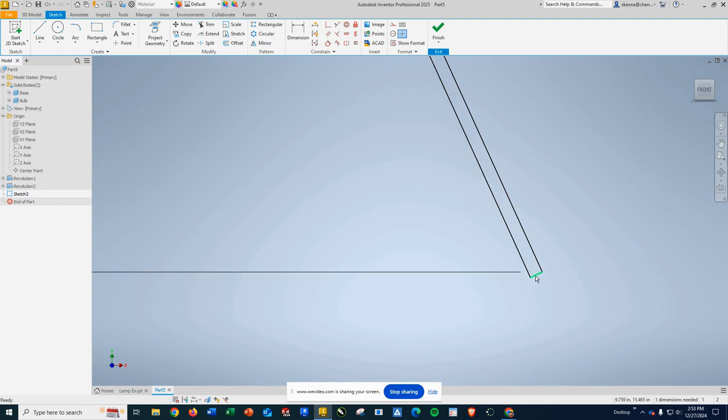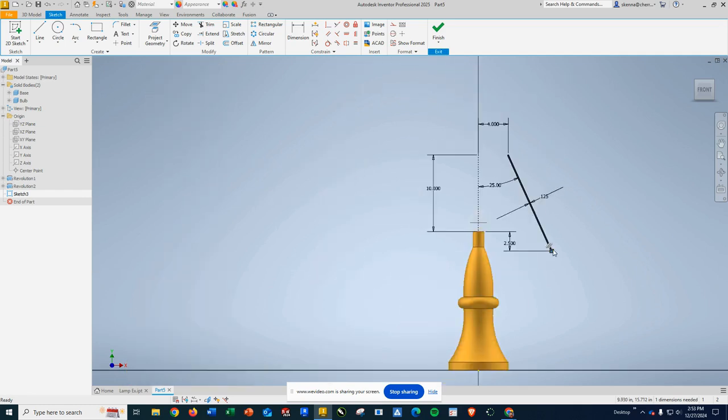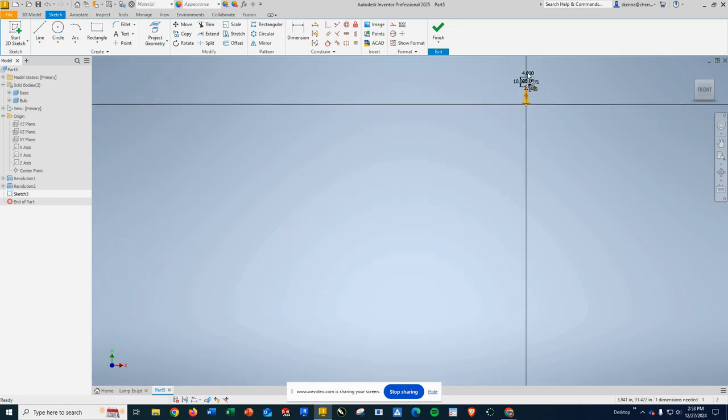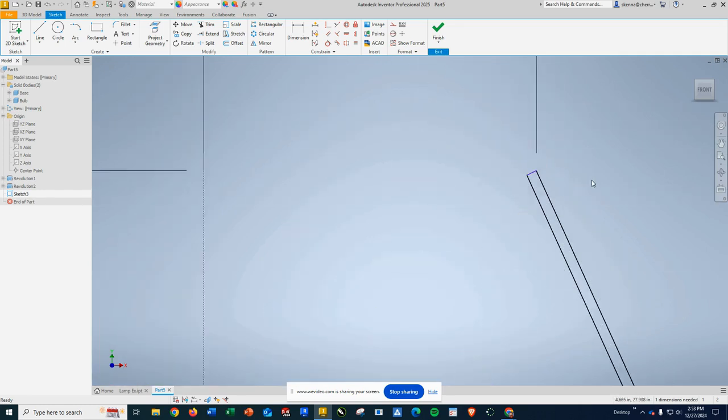I'm going to try something that is parallel with the top one. Okay. And I'm going to check the top one to make sure we don't have another one on there. So that's parallel there. Okay. What I am going to also do is use my perpendicular one and go from the endpoint to that endpoint. And now I am fully constrained. So that's what it needed, was just that quick little relation.